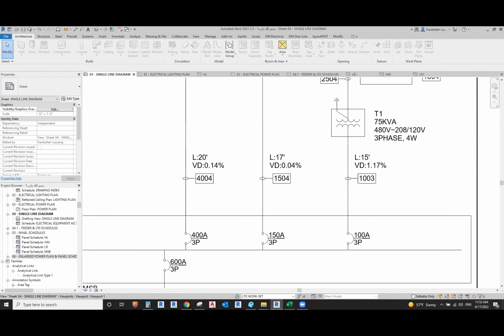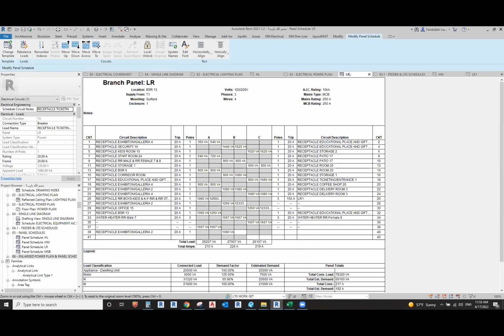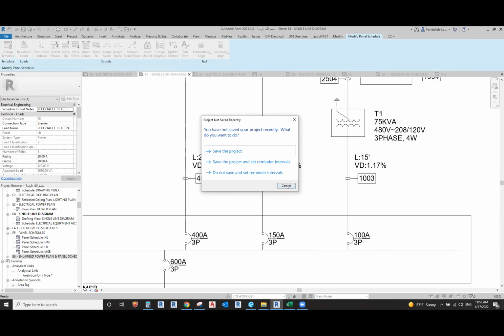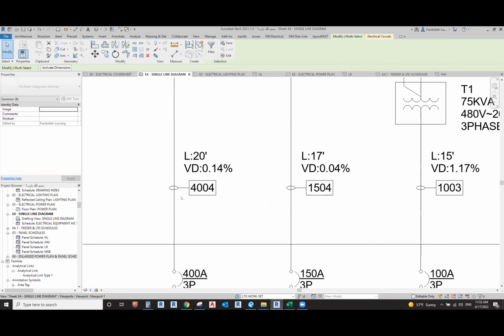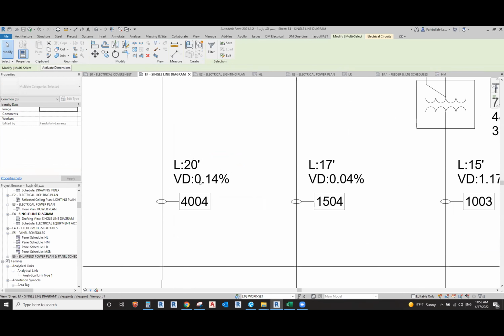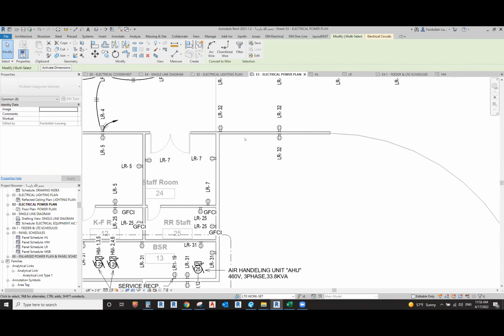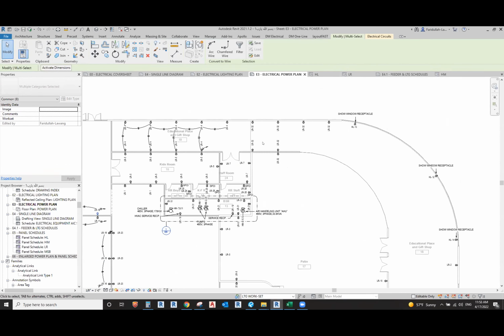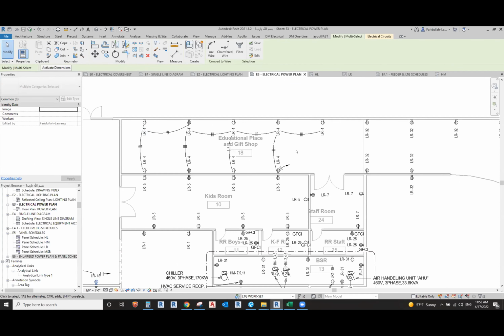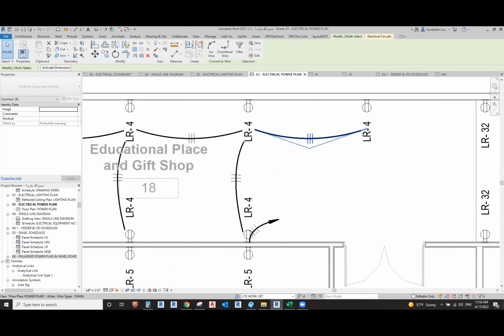Right? Yeah. So the idea is, if you open any panel, you will see that the voltage drop in the feeder should be not more than 2%, and for the branch circuits should not go over 3%. Meaning like this, all 1, 2, 3, 4, 5, 6, 7, 8, 9. The receptacles are in one circuit, right?